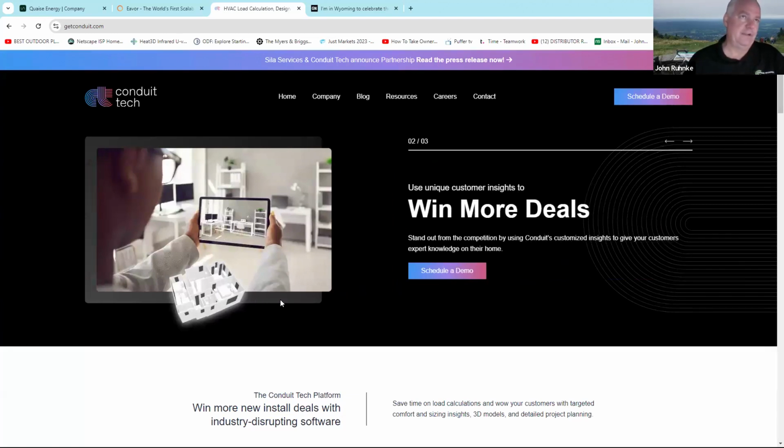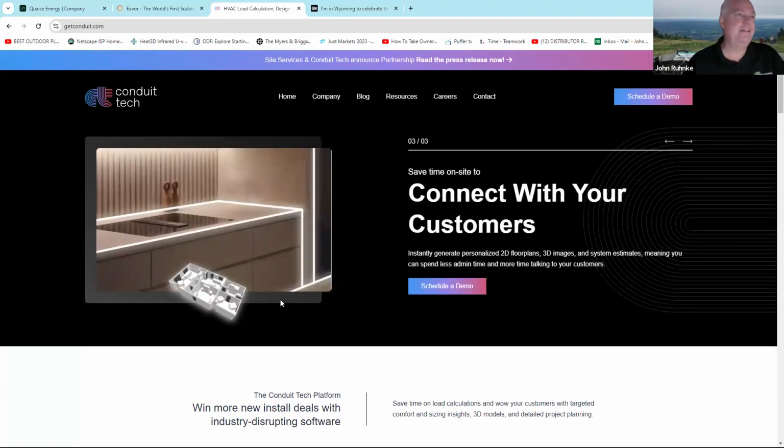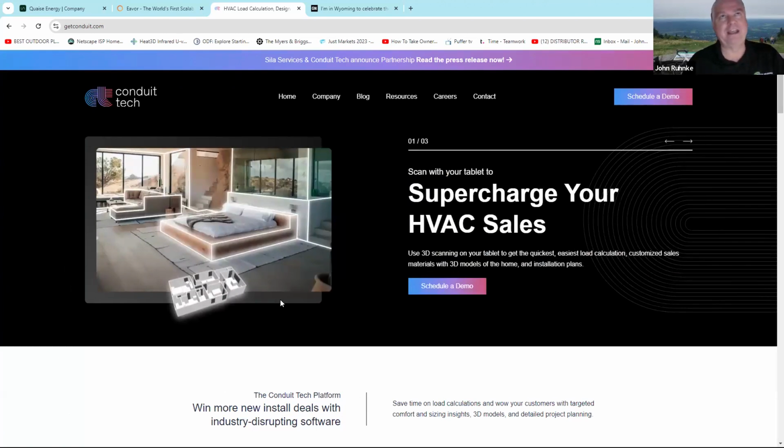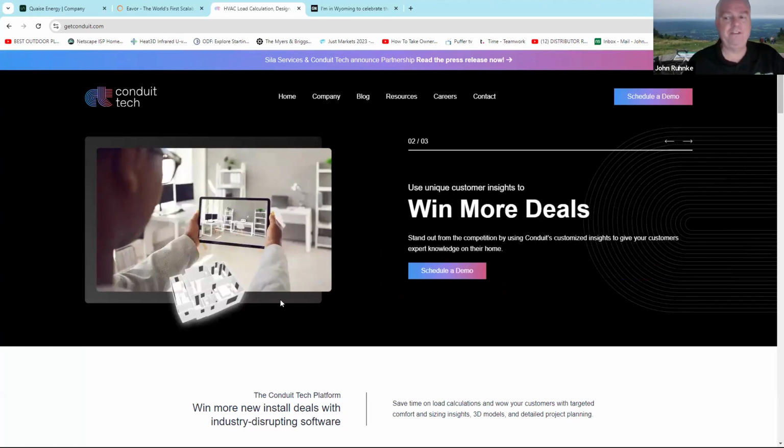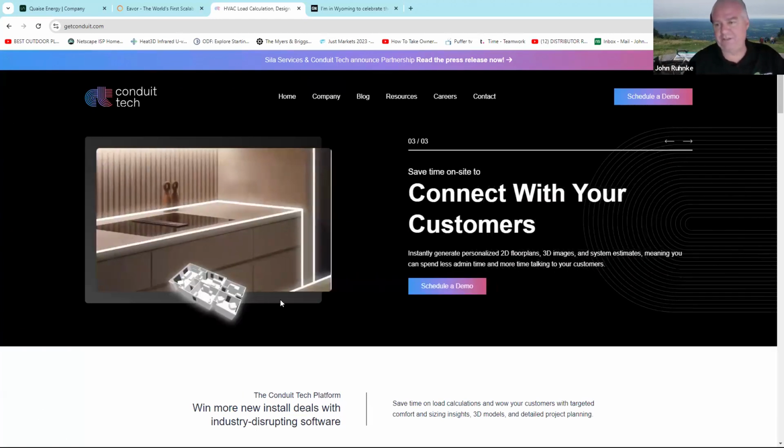So the compressor is using energy to run. If you have a coefficient of 3, that means the compressor is running at one part, and then you're grabbing 2 parts energy from the air to make 3 parts of energy that you provide to the house to heat it. So you're able to provide more BTUs to the house. Thus, you can go 300% efficient, 400% efficient. So you can go over 100% efficiency.